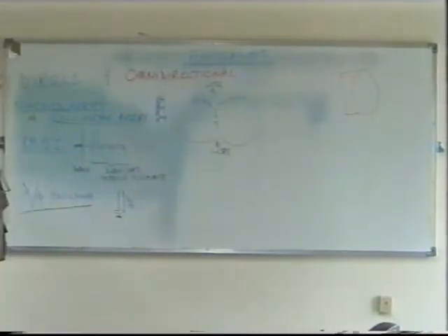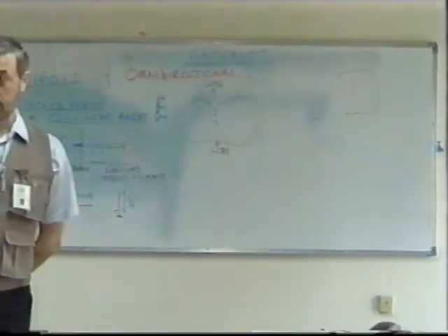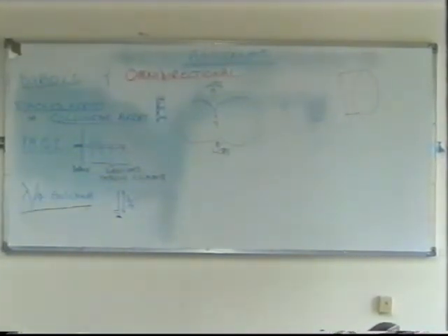So the HF band can pass through the building. HF is no problem. As we go to the lower bands, no problem at all. You go to the lower frequencies, like HF, MF, LF, it becomes easier and easier to pass through buildings. In fact, LF will actually pass into the ground or into the sea to a certain extent, a few meters. Not very far, but it will go to a certain extent.